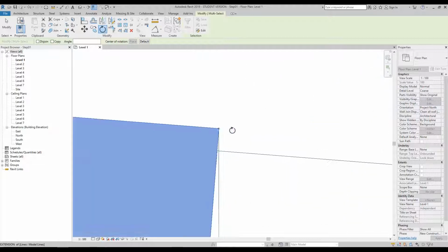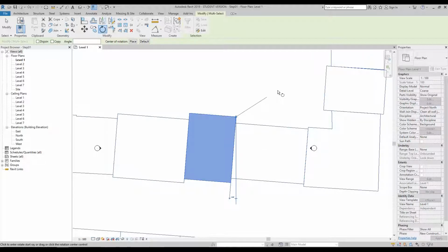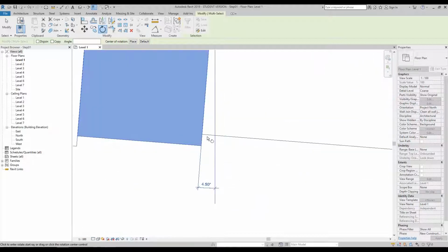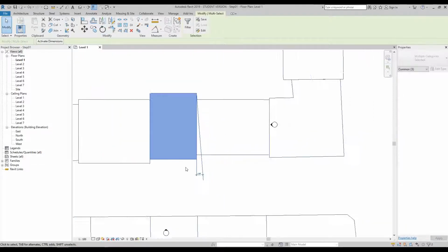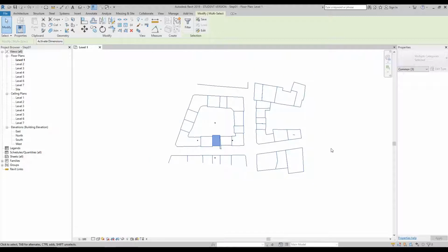So then if you go down to this top corner here and then click again, the rotation will be on that point. So the next thing we're going to do is highlight the DWG on the black footprint, click once and then rotate it to your model line and then click again, and your DWG has rotated. Once you've done that, I want you to press escape once.